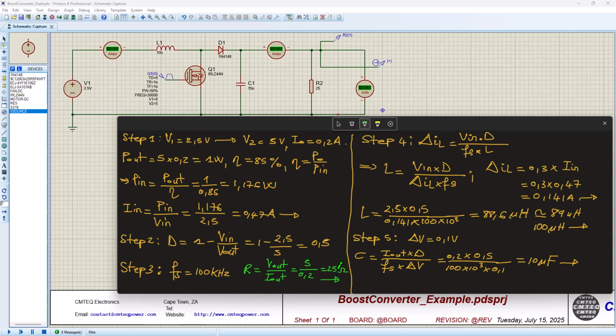So if you reduce this resistance, this current is not going to be able to maintain, and that ultimately needs to increase here. But because we've already sized our inductance based on that, you're going to start stressing your inductance, the ripple current is going to increase, and that means your inductance is going to start reaching saturation, because that is another part that is very important. You need to make sure that the inductance does not reach saturation based on the peak current.